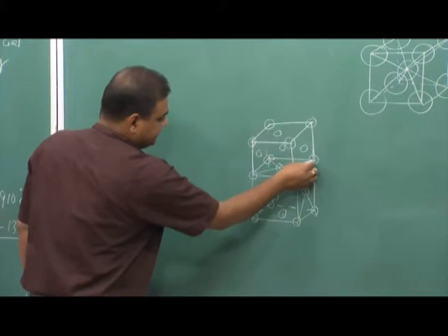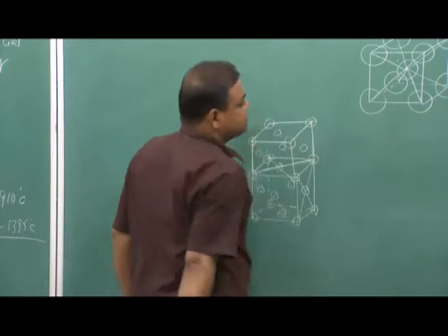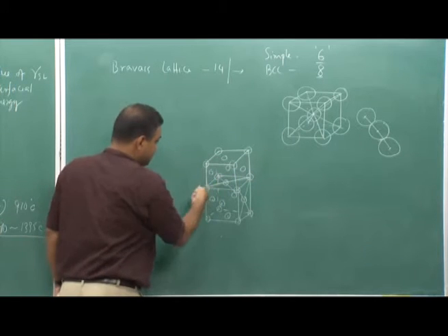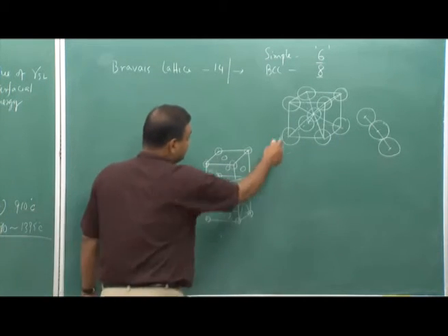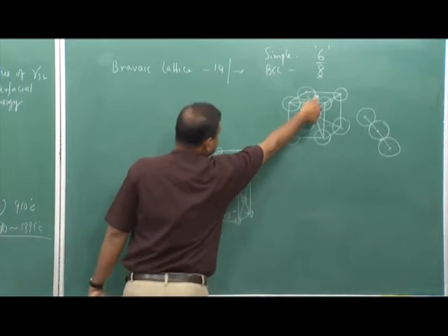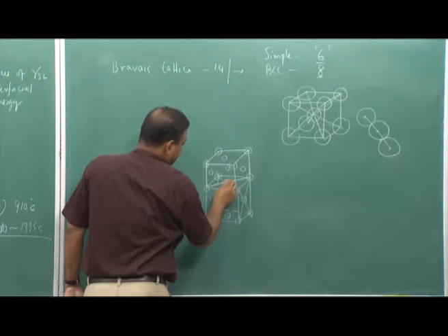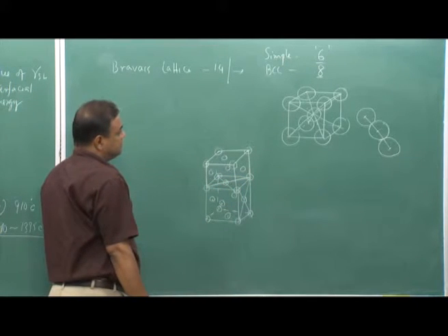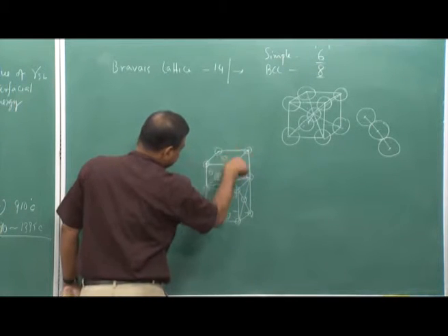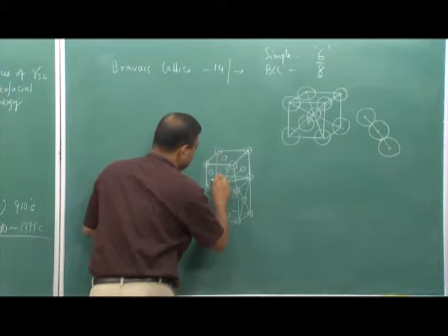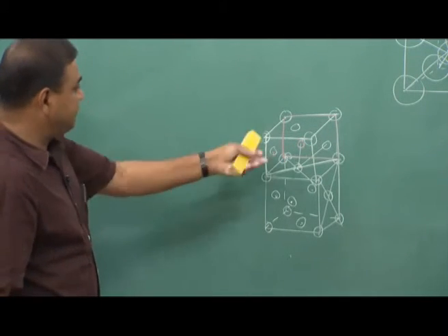Similarly, the corner atoms like this. So, this is the face diagonal. Just like in BCC, where 3 atoms are joined together along the body diagonal, here 3 atoms are joined together along the face diagonal. And if we try to see the nearest neighbor at the same distance, all those joined atoms are at half of the body diagonal there, and here the nearest neighbor atom position is half of the face diagonal. These are also connected to the center atom at the back face, this particular plane.